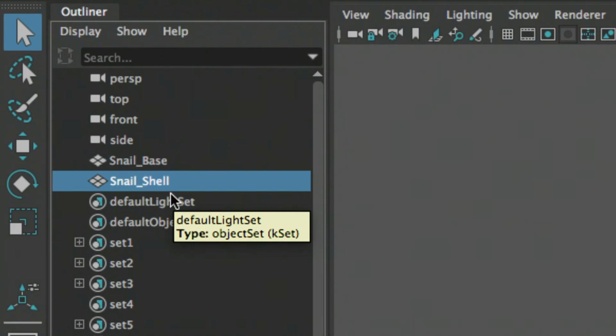Now notice that Maya is adding all those underscores for me, okay? Maya doesn't understand spaces in file names, so don't try to force it. It will never have a space in the file name. Or uppercase letters. Well, no, it does allow uppercase letters, but it can cause a problem if you export it. Maybe it won't read it. There's one other thing that it doesn't support when it comes to file names. I'm trying to remember off the top of my head. Commas, periods, and commas, I think that's what I was thinking of. Point being, name them. It's just as easy as hitting the Return key. Don't make this harder than it needs to be.